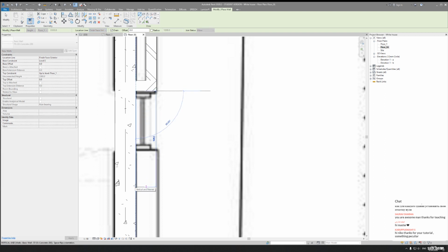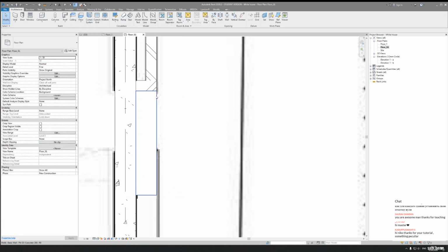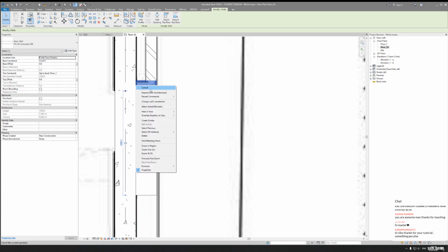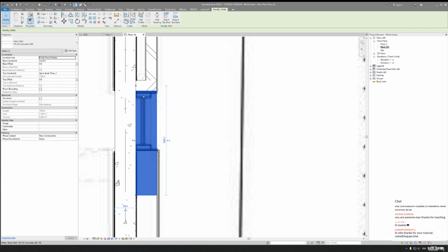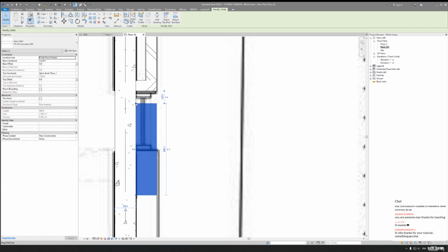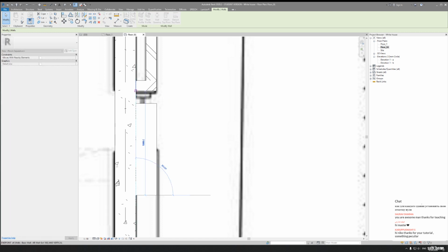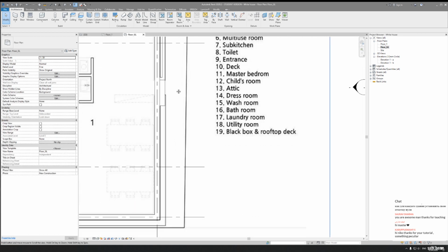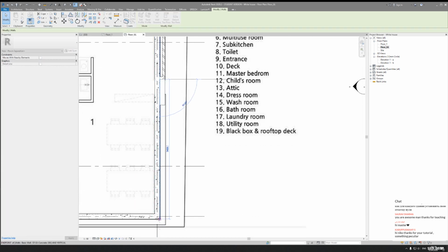But if you watched my previous tutorial yesterday, this is not the best way to start from this intersection. If you did not watch it, I will show you right now. We will continue because we should select it, right click here and you should disable connection with this join. So let's select it, join, right click, and as you can see, it's really hard to find it. No, I don't like this way. I will do it like this: disable join, disallow join, sorry, and let's connect it. And as you can see, now everything is alright. And now you just continue till the end.